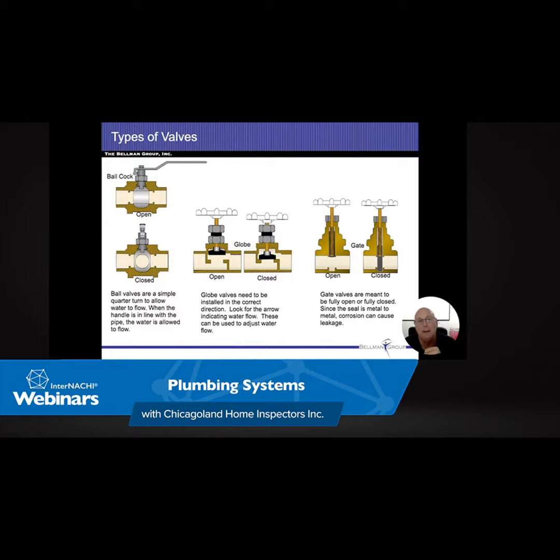All right. Going to the left side, the centrifugal pumps, the water comes in through the eye. So as we're looking on the left side of the drawing, the pipe that goes up and down and goes right into the middle, that's what brings the water in. And as that water comes in, that has to be filled up completely with water. This is not an airtight chamber. It cannot pump air through a centrifugal pump. A positive displacement pump can pump air, but a centrifugal pump cannot.